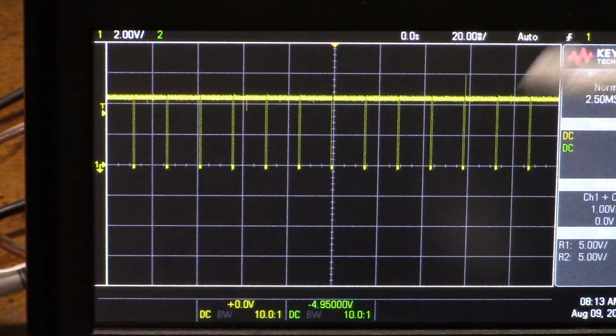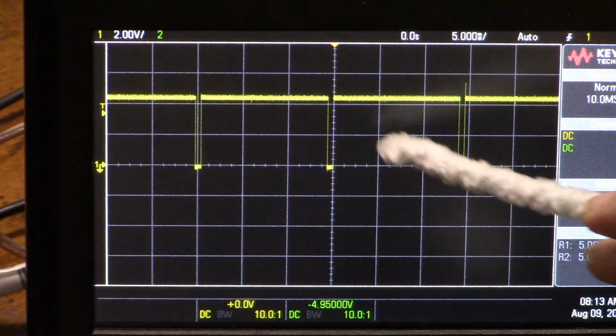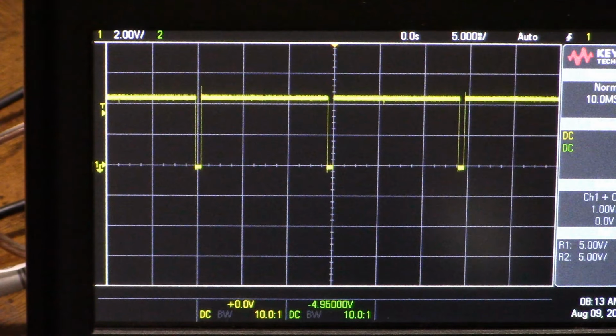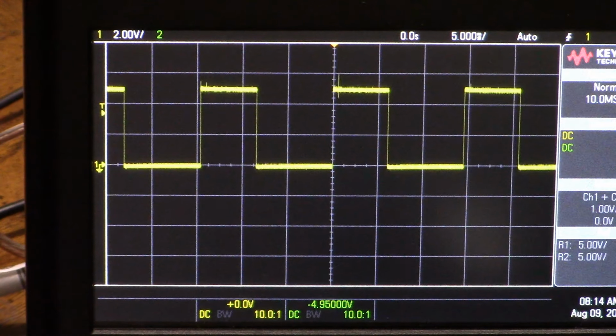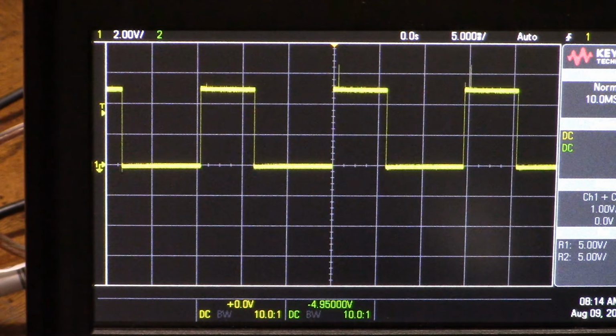And then all the rest of the time it's high. So if I bring it bigger, so this is the 5, 10, 15, that's how it works. So now let me switch my oscilloscope back to the proper output, and here's my adjusted wave. And I will now use a screwdriver to adjust my potentiometer. So this is setting my control voltage.